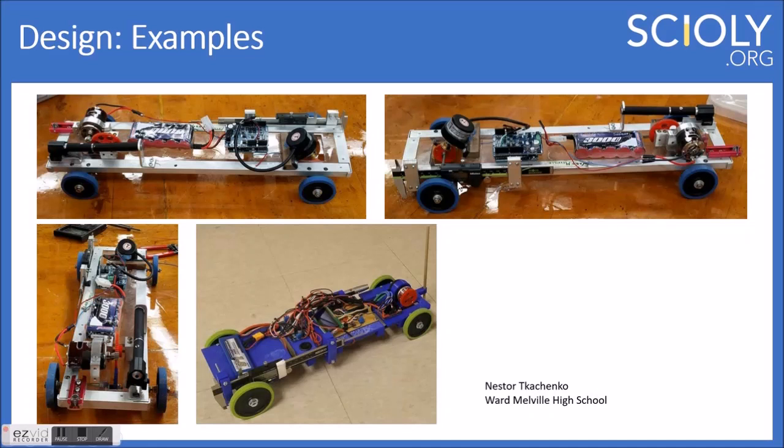He attached the caliper to the axle using this kind of pillow block, and then from there he relied on the play inside of the bearing to be able to adjust it. So moving that caliper adjusted the angle that the axle was at, and that resulted in different changes in the steering.